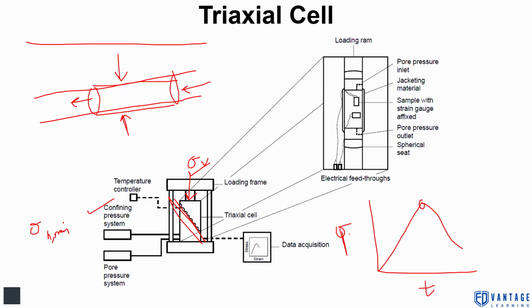And this is actually force that we give in newtons or kilonewtons. And we convert this force to stress, which is force upon area, right? And the general configuration of a triaxial cell is that your confining pressure is given by a radial force, by a fluid, to give your radial stress artificially. That will directly mimic what is happening in the subsurface. So there is a membrane between the sample and the confining system.